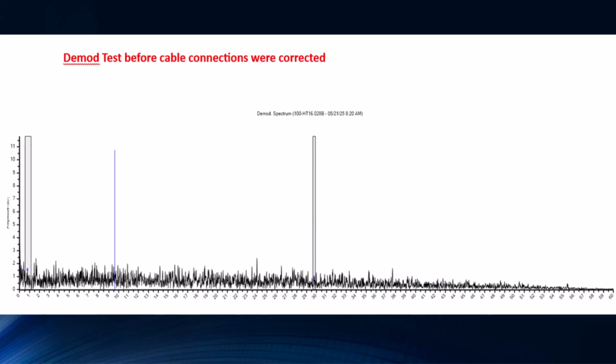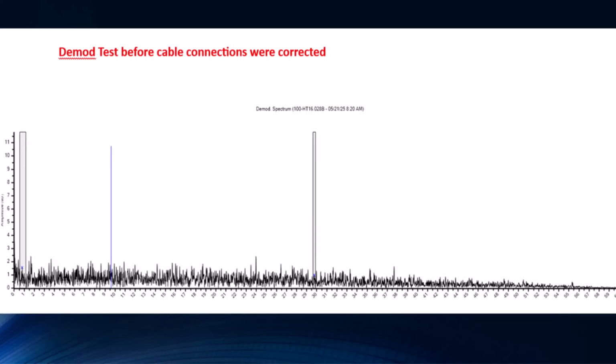I've often heard you say the number one killer to an asset is heat. All of this harmonics, whatever junk you want to call it, noise, is creating excess heat in the cabling. Anytime we talk about power quality issues, be it harmonics, imbalances, things like that, it directly applies to the heat increase in a motor. If you're way underloaded, which they're not going to be on cooling towers, then that wouldn't be as big of a deal. If you're anywhere near full load, now you're just adding excess heat that's not doing any real work.